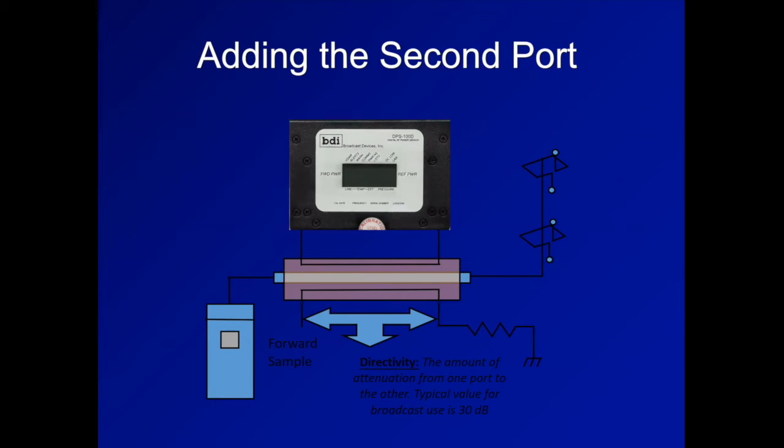Well, if you want to see that the amplifier has, let's say, a 90 dB dynamic range, let's say the noise is 60 dB below nominal level, you need an instrument to measure that has a noise floor that's in excess of the amplifier. So you need something with perhaps 100 dB noise floor.